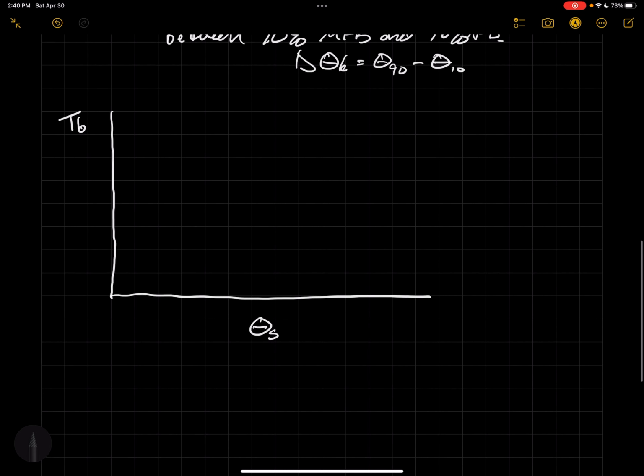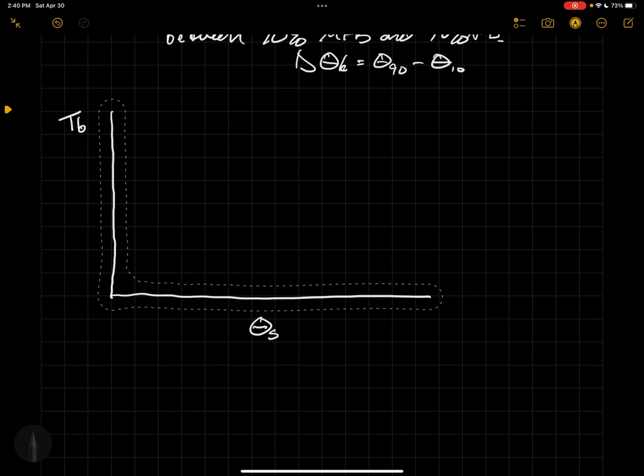When I plot theta s, the spark timing, on this axis here that we're showing our brake torque on, this is now for a given cycle, right? The spark timing was a certain value, and I am generating brake torque as a result of that spark timing, cycle after cycle after cycle.